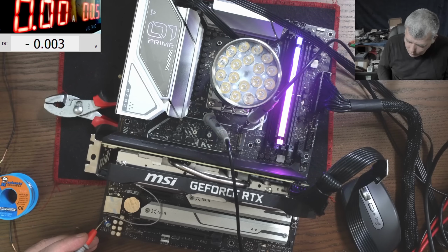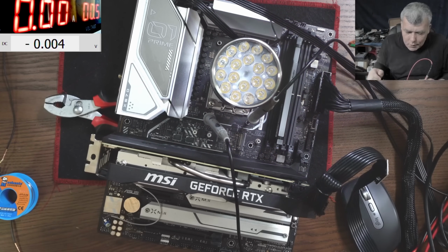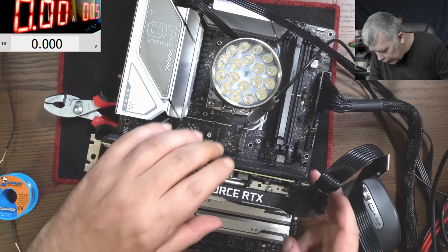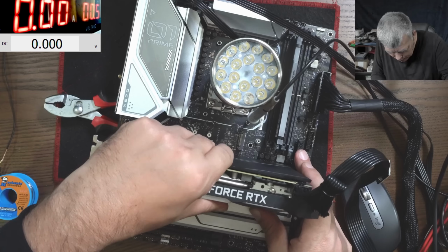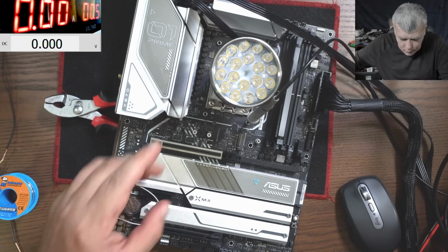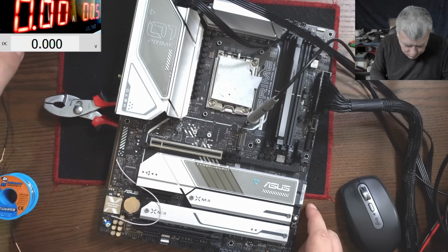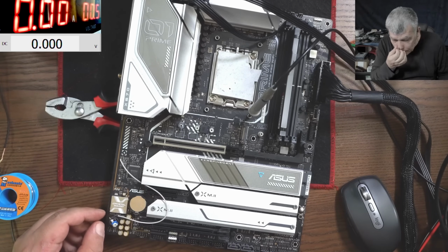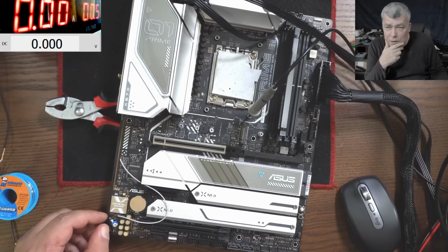And 0 volts on that pin. Okay, it will not work. So what do we need? We need a divider, but the problem is where you can put a divider on a motherboard. I mean, if I leave the adjustable resistor here, it will be knocked off. Or I can do a divider with a resistor, but I don't have an SMD resistor, just to find a random resistor on the motherboard.